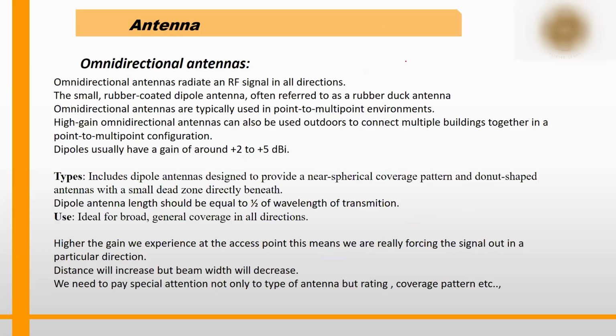So for example, if you are sending a signal like this, but this one is oriented a little bit like this, then there is some aperture angle. If they are getting 60 to 70% of the radiation within that aperture angle, then it will be able to understand the ones and zeros. If it is not able to hit that particular aperture point, then the signal will be lost. Maybe with less than 50%, it is not able to understand.